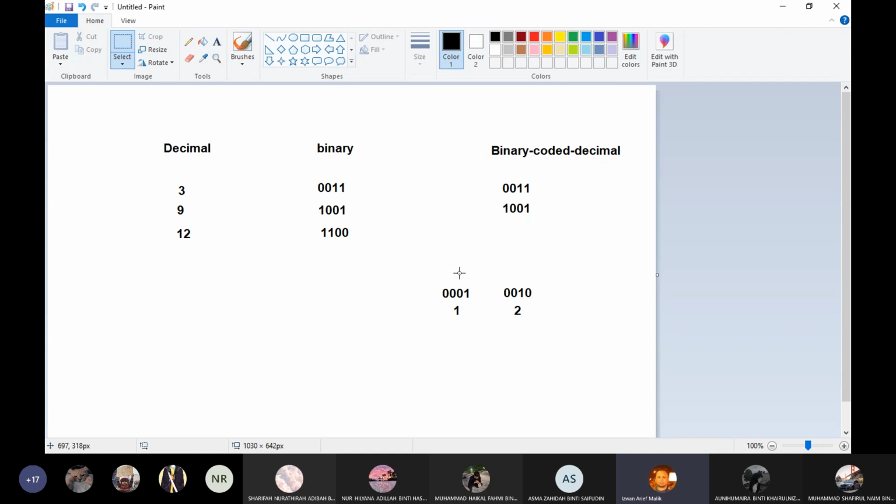When you want to represent numbers which are greater than 9, for example 10, 12, 100, thousands or anything which are larger than 10, you should be using more than 1 decoder. Meaning here if you want to output 12, you need to use 2 decoders. The first decoder outputs 0010, the second decoder outputs 0011. Only then can we display the number 12.